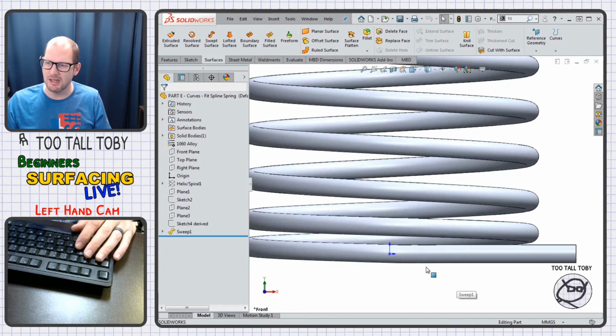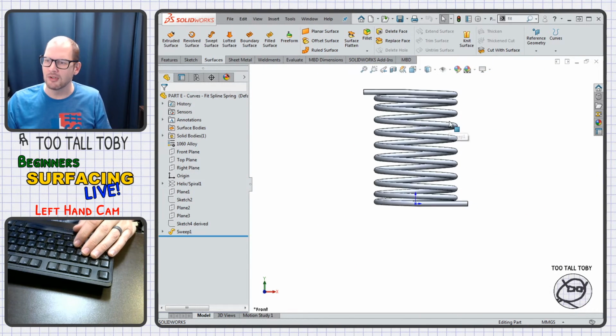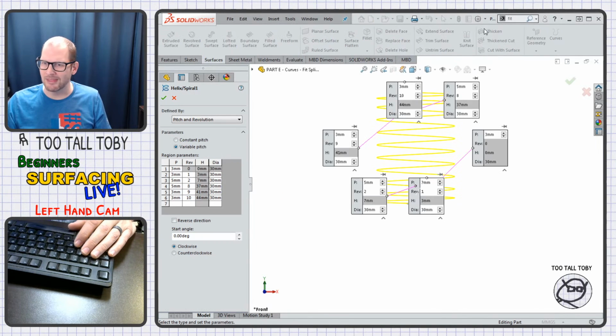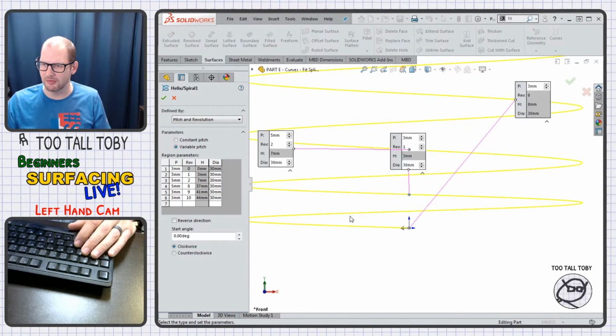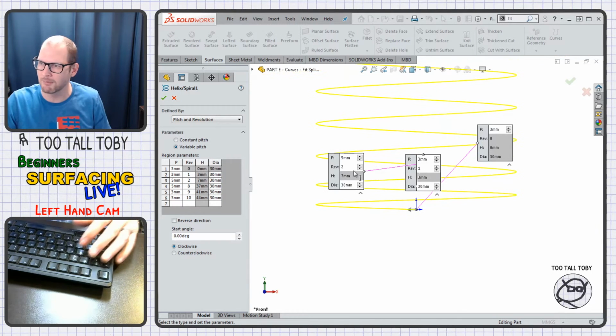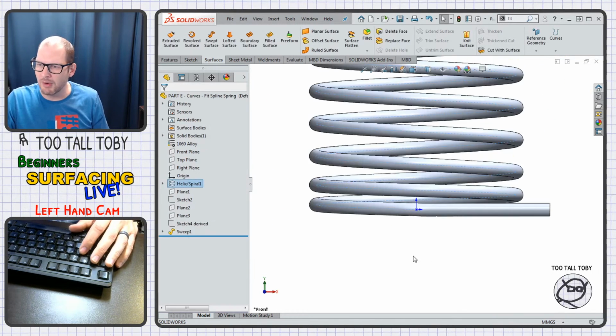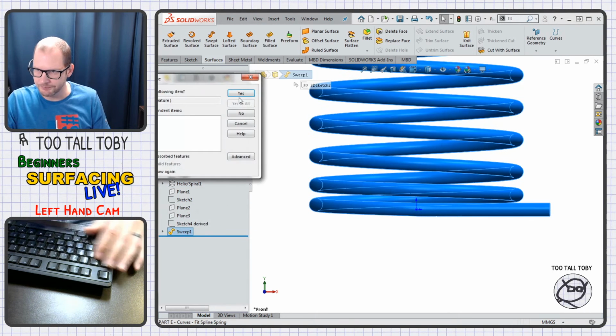Now the reason that's super beneficial is because it means that you can automate, or at least significantly simplify, the transition into a helical path. So here you can see that I've got a helix that's defining the path of a sweep, and it's a variable pitch helix, so it's starting out looking like it's a little more compressed, and then it's going up. And then what I wanted to do was create a transition running into that helix.